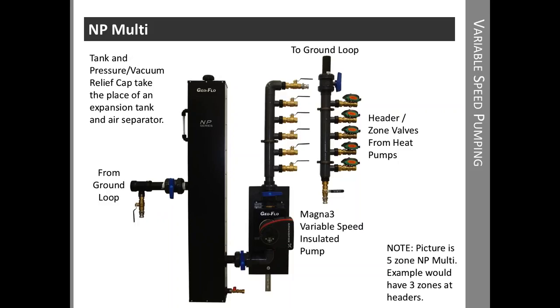Okay, here's another question that just came in. What are the zone valve choices for this product? And the picture here shows the Taco GeoSentry, which is a nice choice from a cost effectiveness standpoint. This is one choice, and it's good up to about 4 tons of equipment. It has a CV of 8.9, so much above 12 gallons a minute, our pressure drop can get a little bit high. So this is also available with the Belimo valve that has a CV of 30, and that'll take us easily up into the 6, 7, 8 ton range. These are 1-inch connections, so you wouldn't really want to go much above 7 or 8 tons on an individual circuit, just because of pressure drop. In fact, when we select this product, we want to go with the largest heat pump first, so that most of the flow gets diverted to the first one and then the next one and so on.